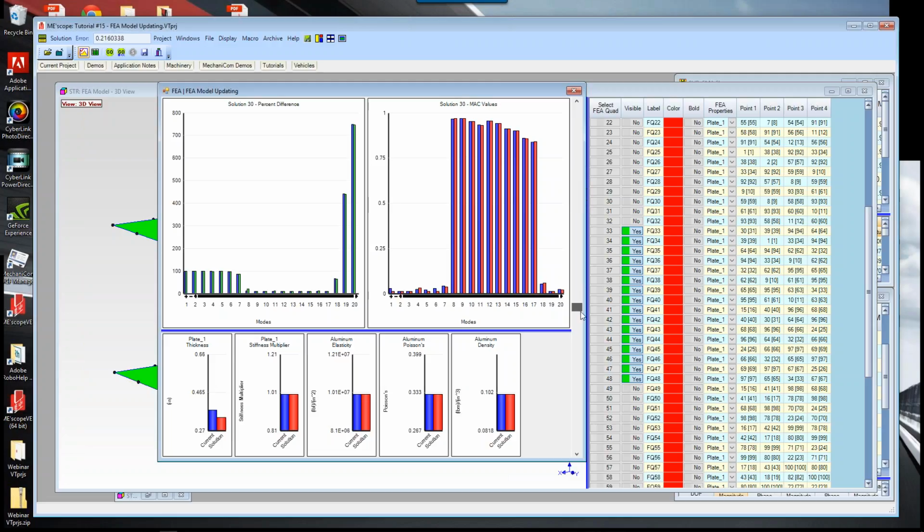errors are changing. So this is an exhaustive search method that tried all of those different solutions, and you can see now when I get down to some of these very poor solutions that the mode shapes don't match up very well anymore, even though the frequencies are not so bad. So this graphics allows me to pick out, I may not want to pick just the optimum solution, which is this one. I may want to pick one of these other ones because it's physically easier to modify the real structure. And any one of these solutions is still quite good.